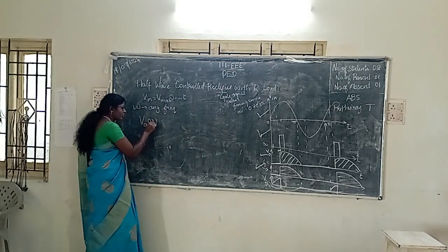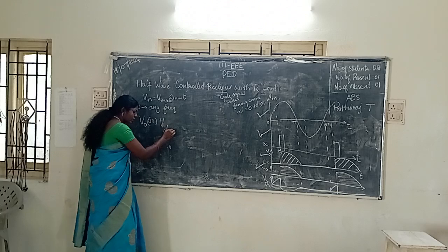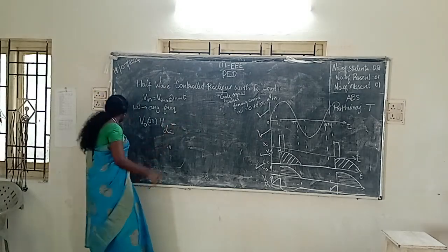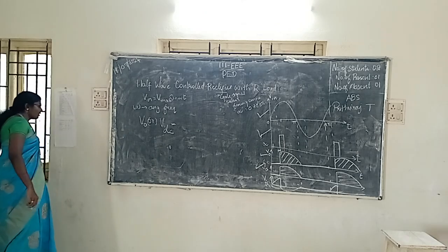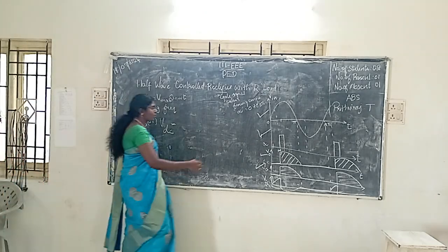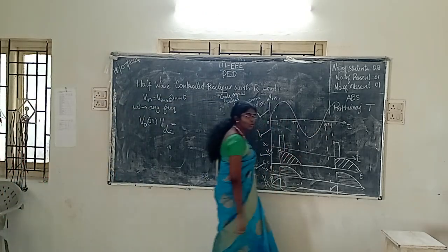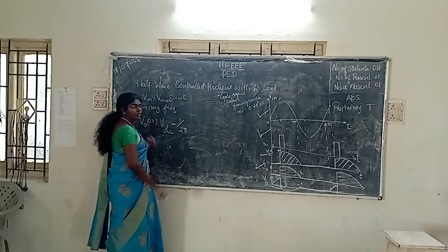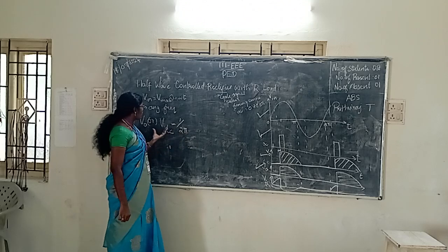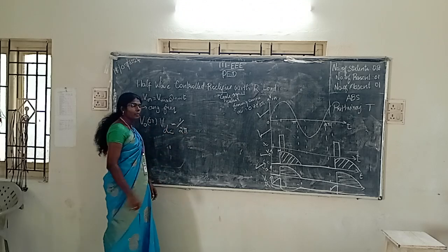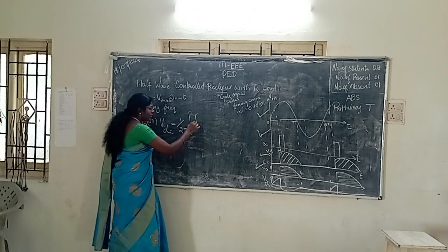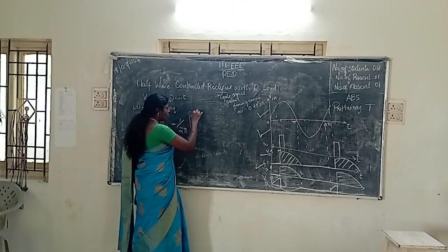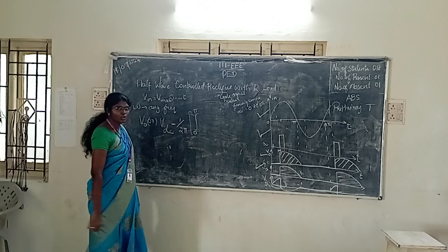Output voltage can be in the nature of DC. Okay. So now for a complete cycle, positive and negative, the complete cycle is 0 to 2 pi. So it will be 1 by 2 pi. Okay. So the voltage VDC is equal to 1 by 2 pi of, during the first half cycle, alpha to pi.